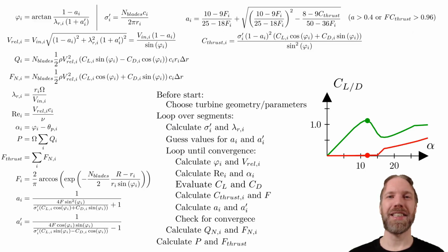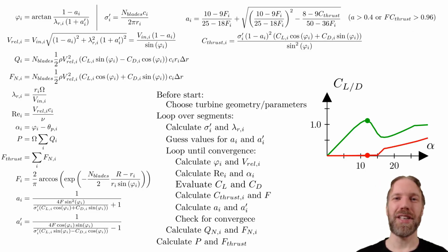I also want to mention that this particular method will not always converge. This is a standard problem of solving nonlinear equations though, so you can try another numerical scheme if you're experiencing convergence issues. Now we're going to run the model and see what we get as results. This method will use the equation I just showed. The minor modification I've done is that I have limited the actual induction factors to values between 0 and 1. I also implemented the bisection method for increased convergence.